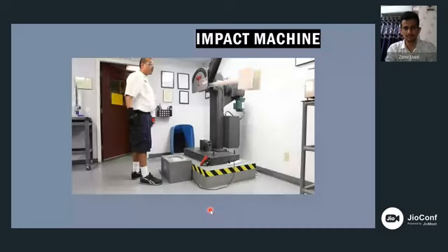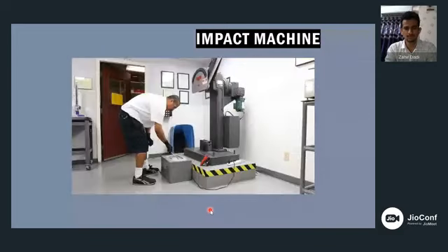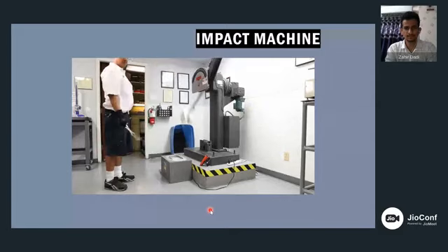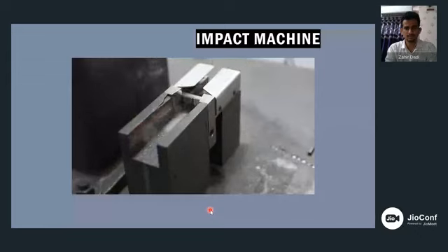To begin the test, the Charpy hammer is lifted into position and held in this position until the test specimens are cooled to the required impact temperature. Following this wait period, the Charpy hammer is released, the impact is administered, and the impact absorption is measured. This process is repeated a total of 3 times on 3 identical specimens, and the average of all 3 measurements is reported for the set.